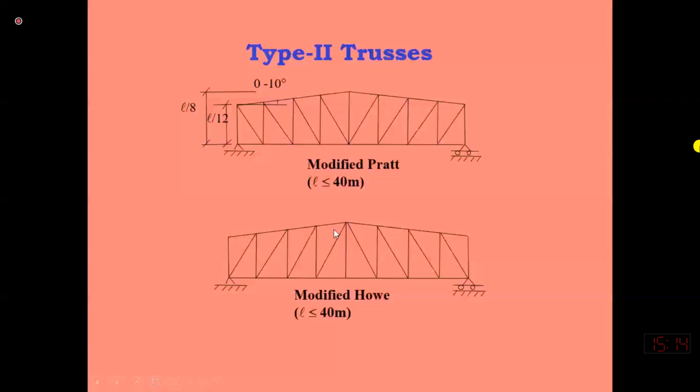So trusses are used where the span is very large and we want to reduce the weight of the structure. So we want to reduce the weight of the structure, so we are using skeletal members. But in a typical hot rolled section, if we select a larger depth, then we will have a lot of material between these triangular segments. So what we have done is make a beam with the help of skeletal members.